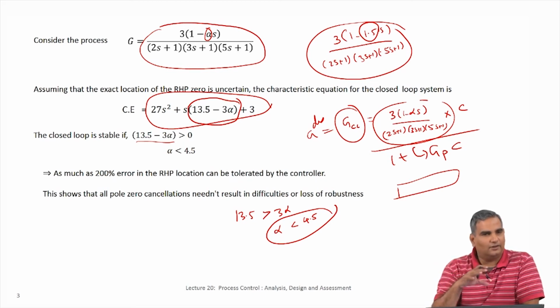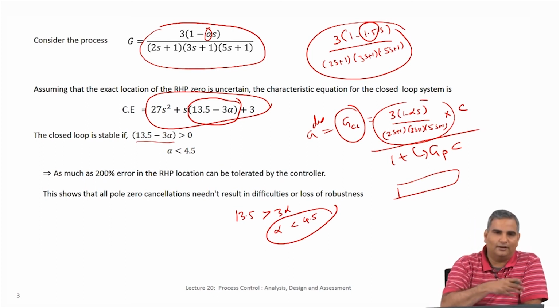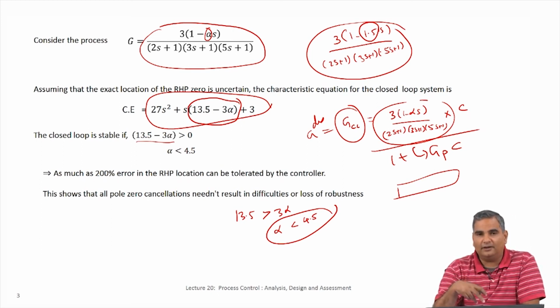Okay. So, in the other case also model parameters are very much there, but they get buried into your PID controller. Here it is more explicit, and as you go more and more advanced in control topics, it will become more and more explicit in the controller calculations themselves. So, even here for example, though I say the controller is 1 over GM and that is where the model explicitly comes, ultimately we got a PID controller. So, all the parameters were used and implementation is PID. While this is a little more explicit than your Ziegler-Nichols tuning, it is not used in online controller computations.